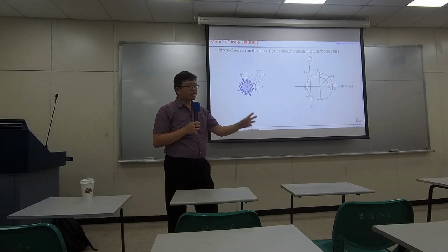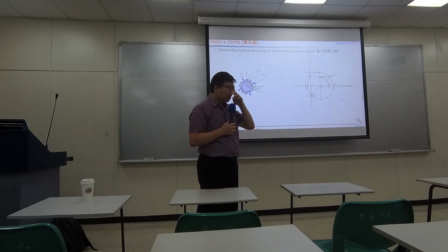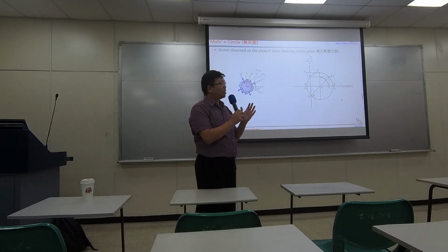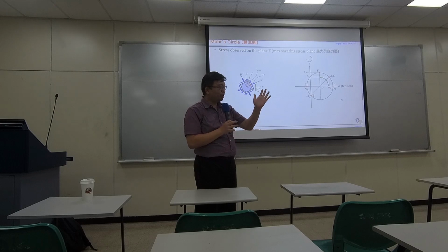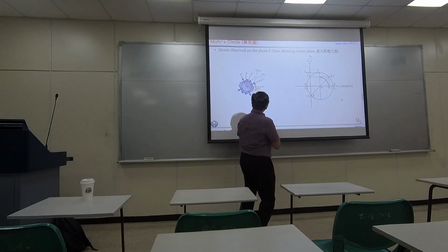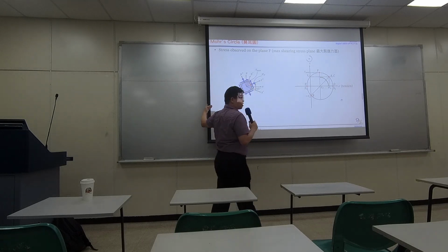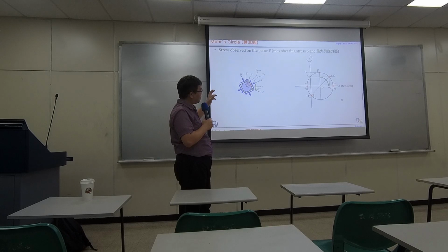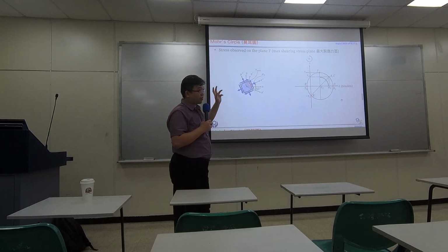So if there's a material that is afraid of shearing stress, most likely when it breaks along the shearing plane, it's gonna break along some coordinate along this direction or this direction. Because this is the orientation where we have the largest shearing force.